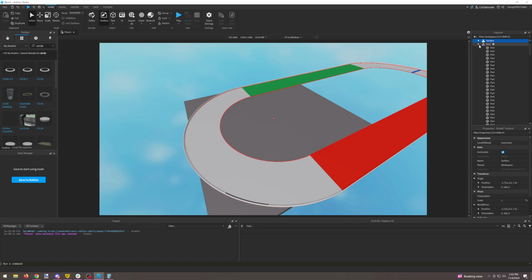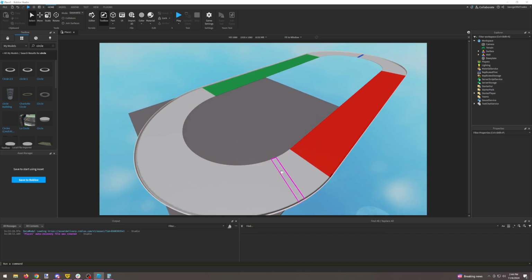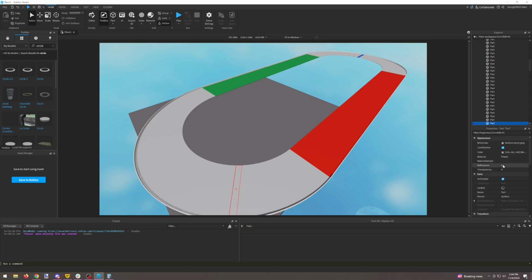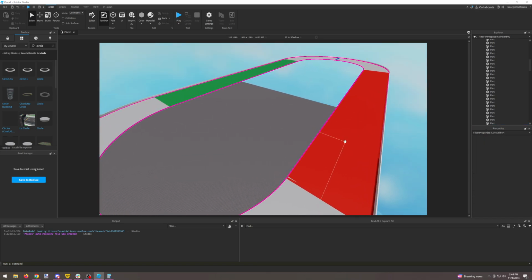When it comes to the dirt layer part of this, what we'd end up doing with the surface. So first things first, these parts are fine at 12 width. I do not recommend ever going over 15 width for a dirt part. After 15 width, you're going to start to lose some of the quality of the hits. It's going to draw weird lines essentially.